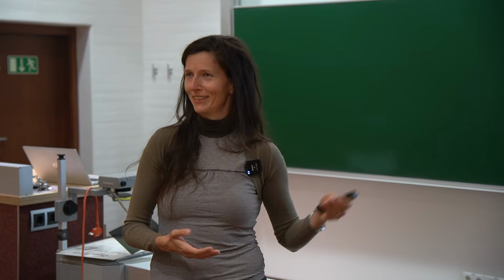And keeping in mind these numbers, when I already mentioned doping of semiconductor, where we can add atoms of different materials, that gives you already the idea how many atoms per cubic centimeter we have to add, so that we add additional holes or just additional electrons, so that we can control the conductivity. It has to be above the intrinsic charge carrier concentration at the temperature where we use it,